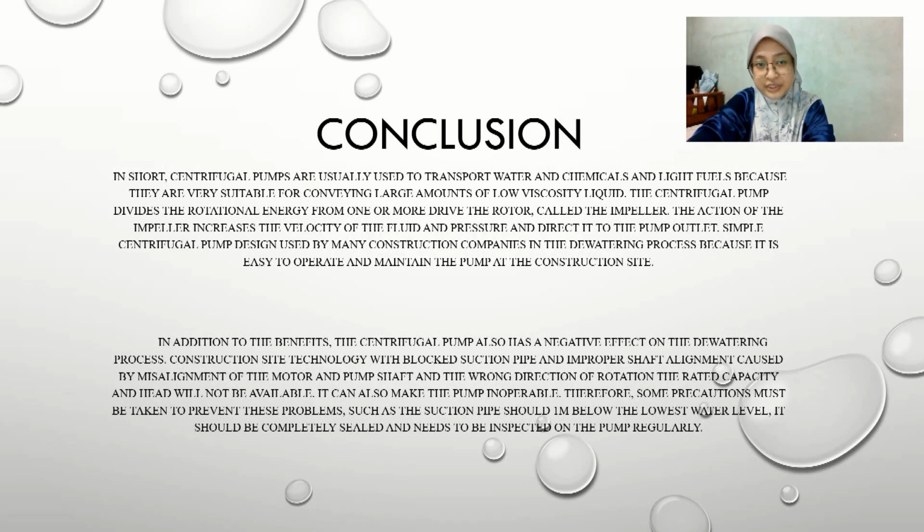As a conclusion, in addition to the benefit, the centrifugal pump also has a negative effect on the dewatering process. Construction site technology with a blocked suction pipe and improper shaft alignment caused by misalignment of the motor and pump shaft and the wrong direction of rotation, the rated capacity and head will not be available. It can also make the pump inoperable.